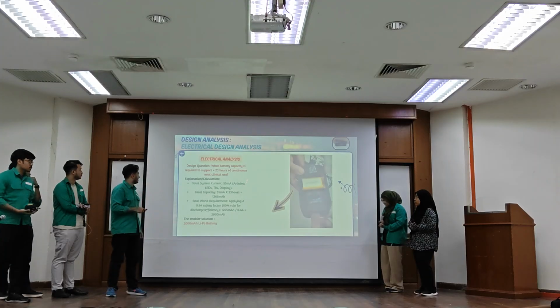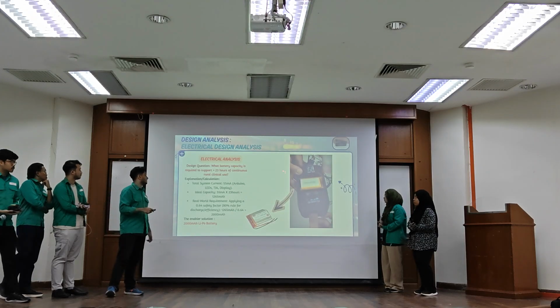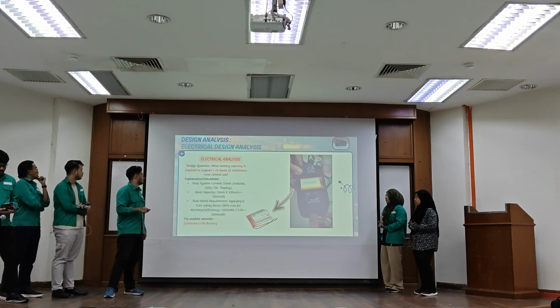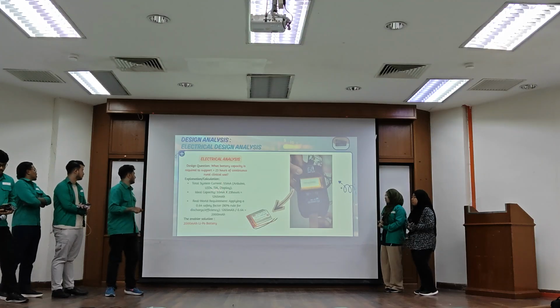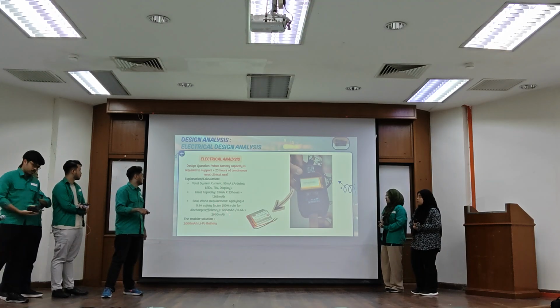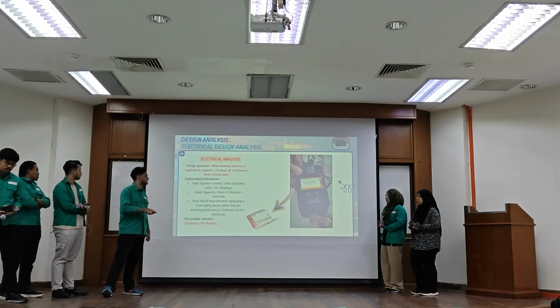The last one is electrical analysis. Our engineering target is 23 hours of continuous use, and our usage is 55 milliampere. So we do some calculation here, with the ideal capacity and the overhead requirement, and we get that the capacity we need is 2000 mAh.